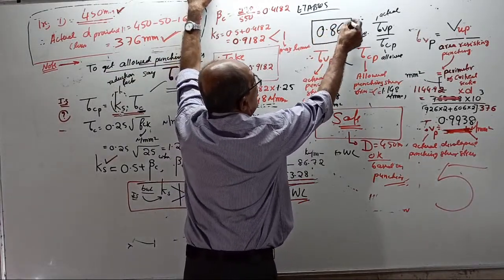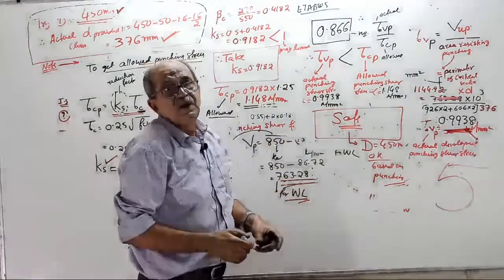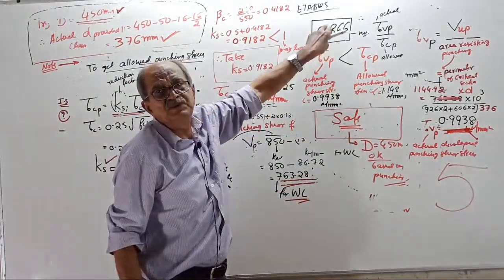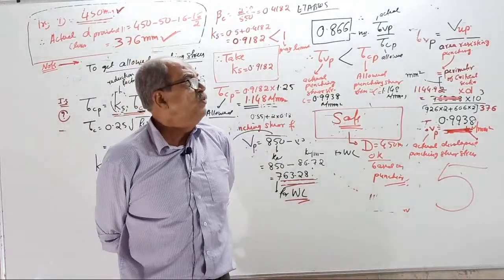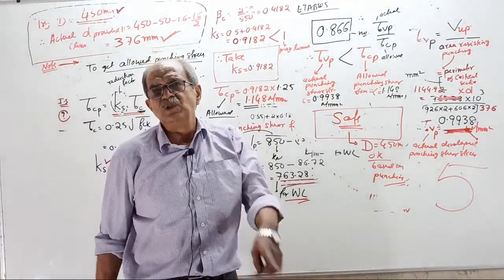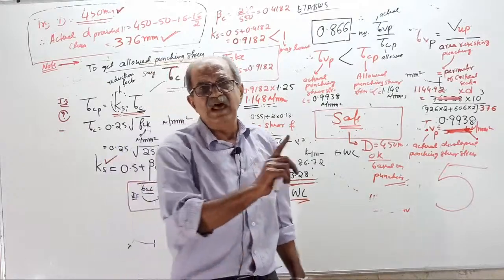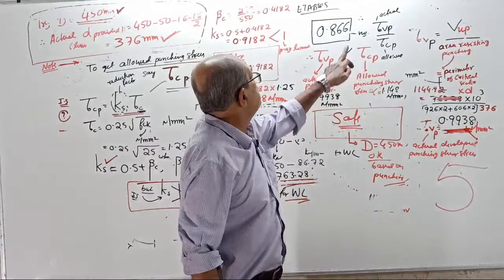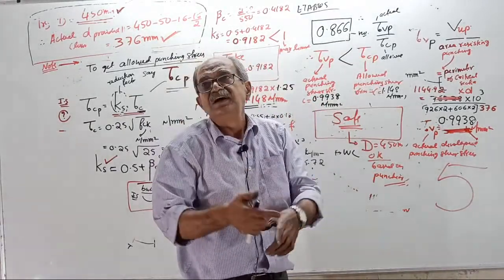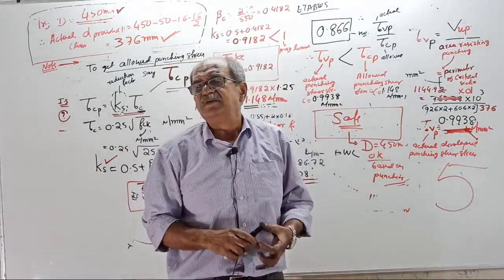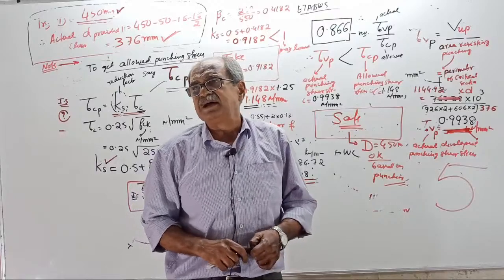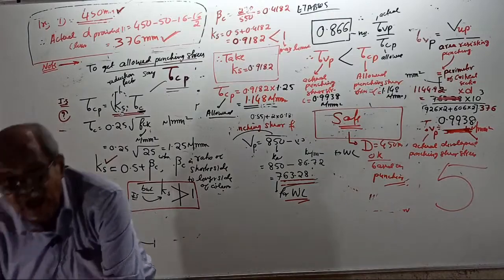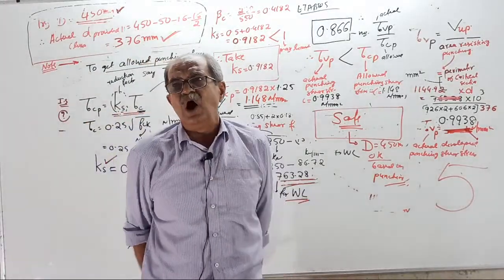At that time, I will tell you, punching shear is safe if this number is what? So when you go to software, I will not explain once again. I already told you earlier, the punching comes in a box. The punching number, we are happy if the number comes what? We want that number to come either equal to 1 or less than 1.